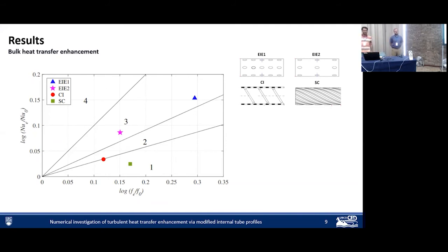So if you plot log-law plots, the proper scaling would not be the inner units, but let's say some equivalent height of the roughness. Yeah, that's right. We did use inner units for most of the normalizations, and that's just because of the established procedures in turbulent pipe flows.